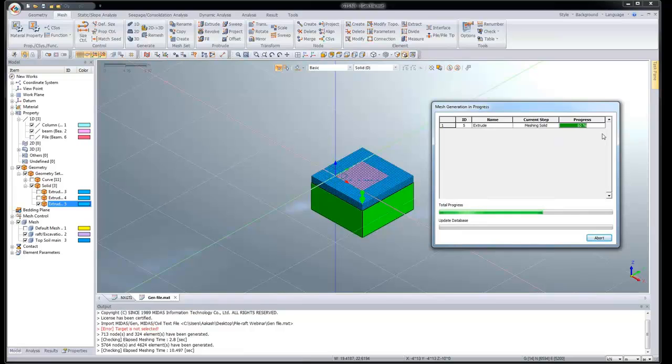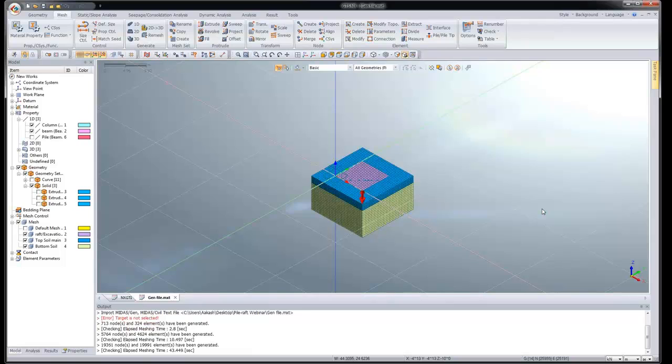So having created the hybrid mesh, the next thing we need to do is generate the mesh set for our pile. Similarly, you have to assign the interface property for the pile. Let's suppose you are considering an end bearing pile, you need to define the tip nodal resistance of the pile, or otherwise you just need to define the skin friction of the pile.